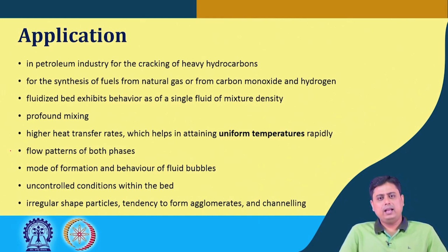This fluidized bed helps in achieving vigorous mixing between the phases, or profound mixing can happen in a fluidized bed. We can have a higher heat transfer rate, which helps in attaining uniform temperatures very rapidly inside the bed, and that leads to the uniformity of temperature inside the bed, which is very essential in several applications.